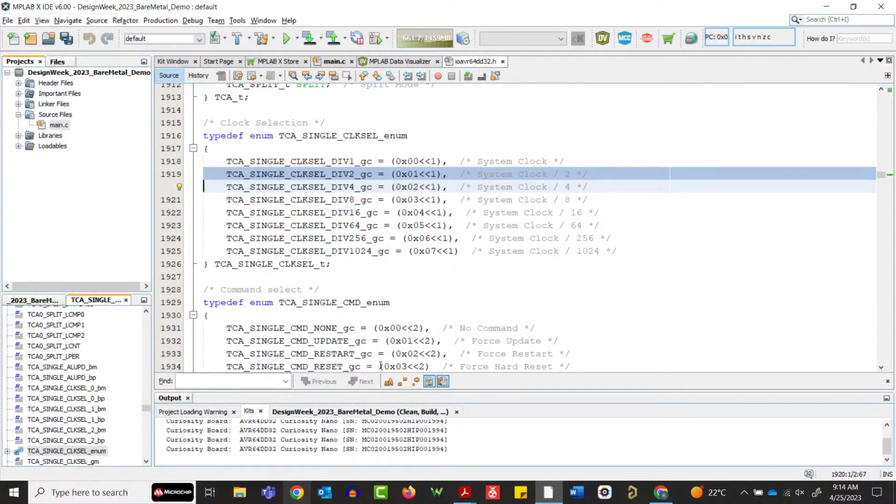All right, so Bluetooth drivers are hard to set up. Would you say this was difficult for you? No, not at all. It uses a USART interface, and so as a result, I just connect my TX and RX pins. I set up my baud rate for this device. It's 115200. And then it just uses a pretty standard frame format of 8 data bits, no parity, 1 stop bit.